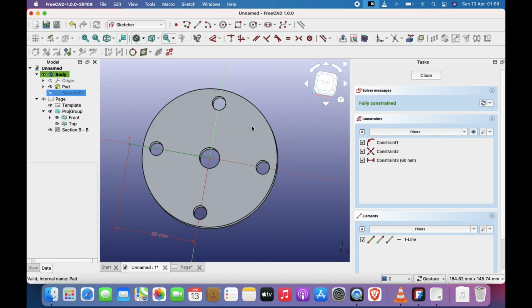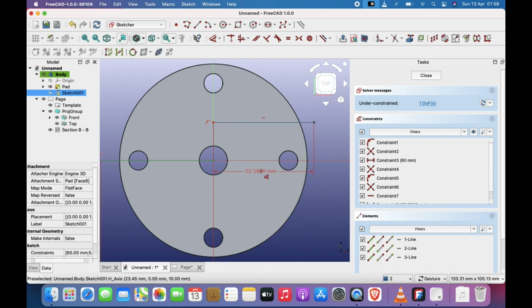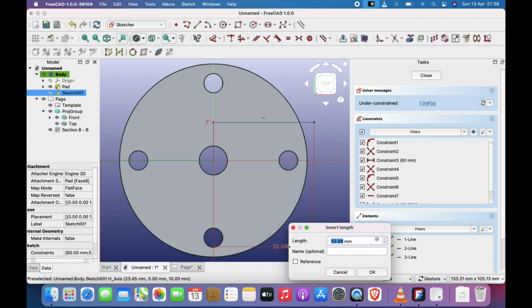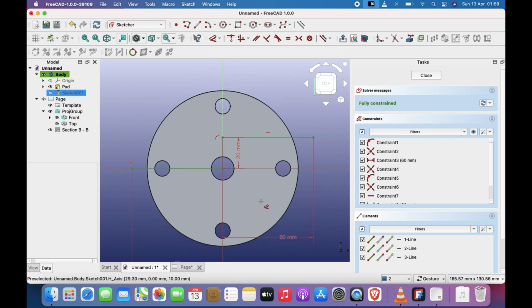So let me go back to that sketch now and edit that line, or just basically add to that line. So let me click on polyline, and then I'm going to click here, click something like this, and perhaps go this way. That's it. Just press escape, and then you know me, I like things to be dimensioned, and let's say that is 60, and let's use 20 for this. It really doesn't matter what it is. It just has to look like my cutting plane.